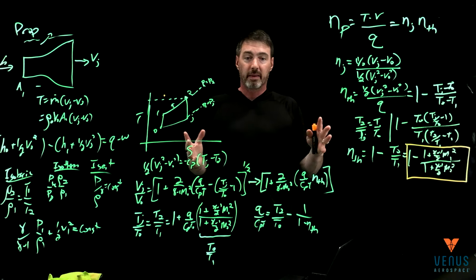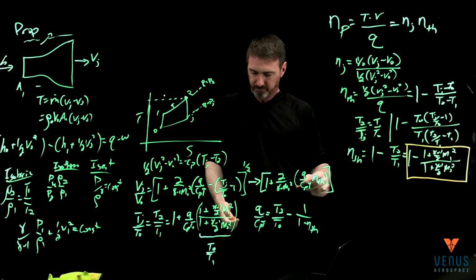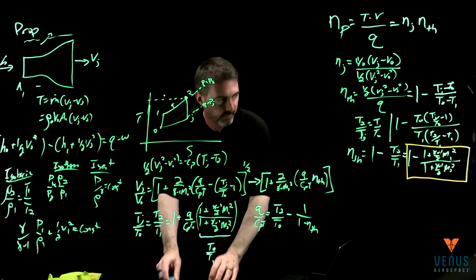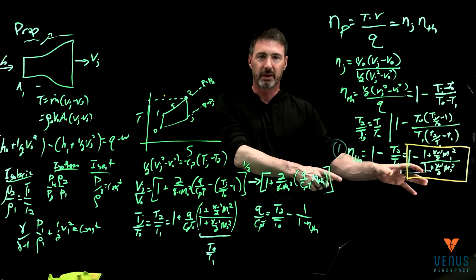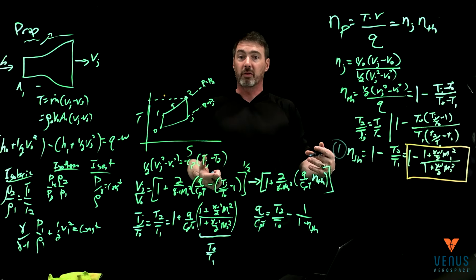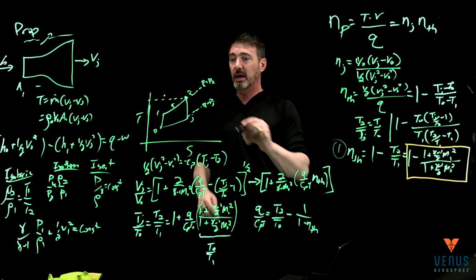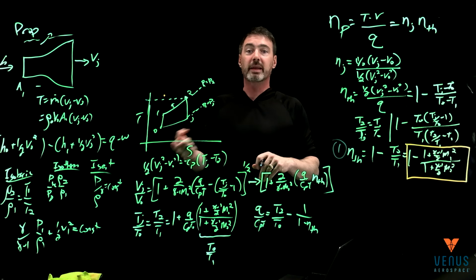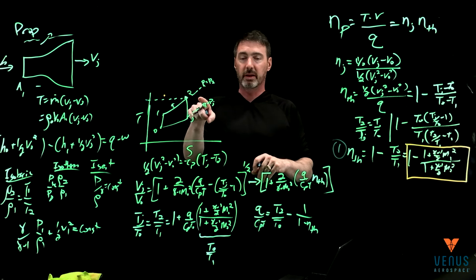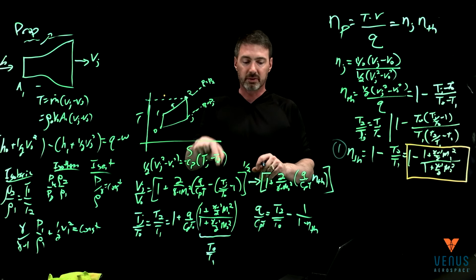Great. Then I'm going to come to this. So that's kind of here. I'll do it in blue. So what you're doing here is step 1: get your thermal efficiency. Now you have your thermal efficiency. Well, what's step 2? Well, I have a material limit here. I would like to add fuel, but I'm going to add fuel, and combustion, only up to the point where this T2 over T0 happens.